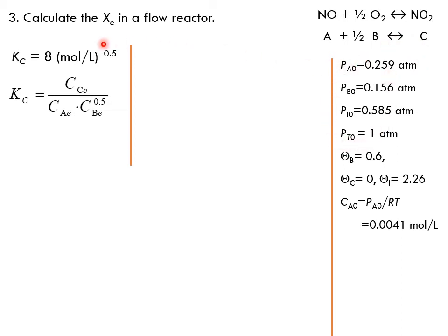What we mean is, if the flow reactor, for example a plug flow reactor, was long enough so that equilibrium conversion would be achieved, then what would that conversion be? So let's calculate this together. Of course, the value of Kc will not change. The expression of Kc will not change with the change in the reactor. However, what would change is the concentration expression.